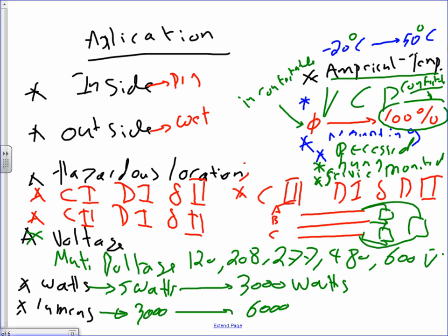So can I take this fixture that's listed and approved and go put it outside, right above your head? No. What's wrong with it? It's listed by UL for indoor use. If you put it outside, you have to have a fixture that's listed for outside. Can I have thumbs up, Chad? Because we'll have discussion on equipment. So the first major decision is, is it going to be inside or outside? That's a major decision for the fixture or any electrical equipment, guys, not just fixtures.